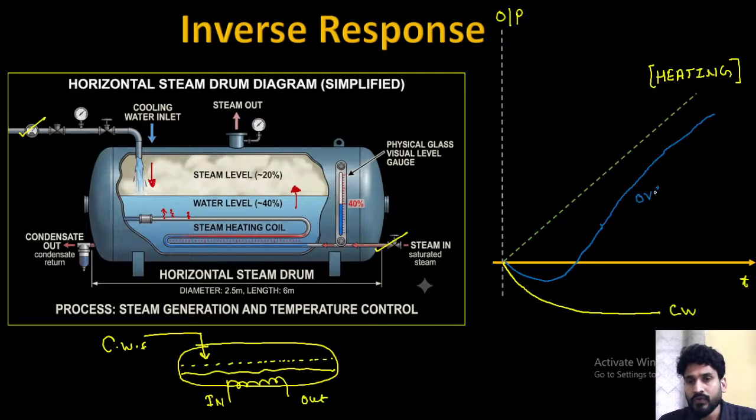So this is the overall response. These are the individual responses. This is the steam coil response, and this is my cooling water response. It is clear to you? This is called inverse response.